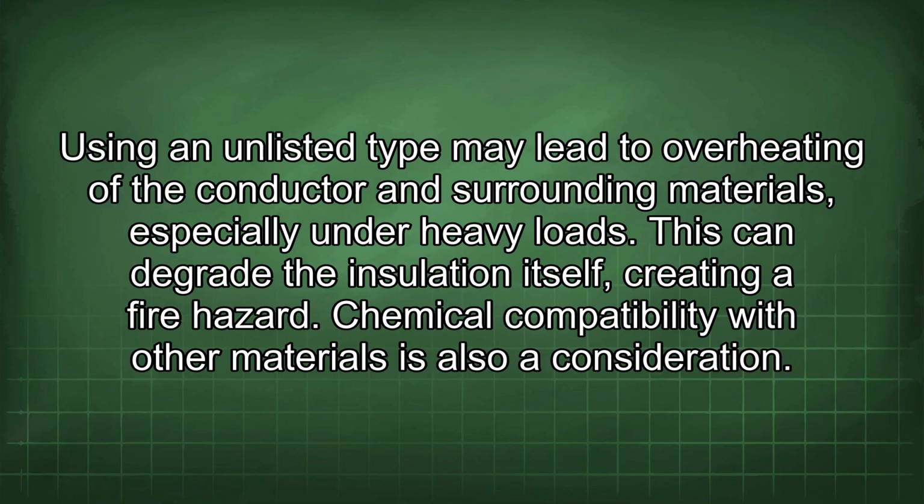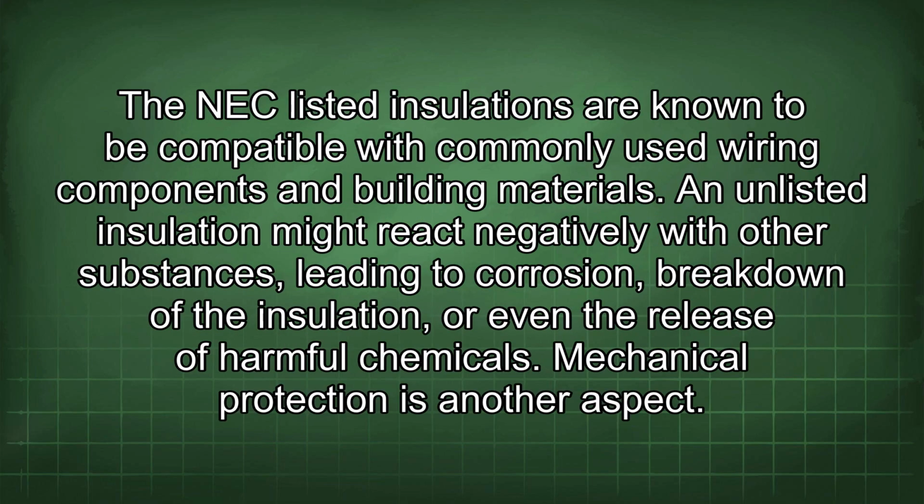Chemical compatibility with other materials is also a consideration. The NEC listed insulations are known to be compatible with commonly used wiring components and building materials. An unlisted insulation might react negatively with other substances, leading to corrosion, breakdown of the insulation, or even the release of harmful chemicals.